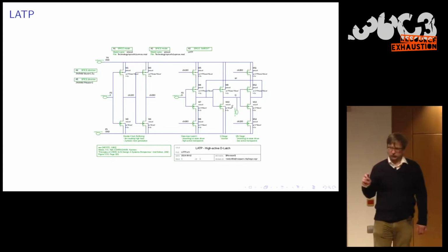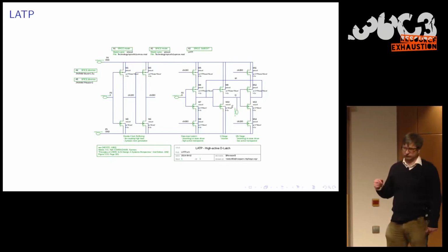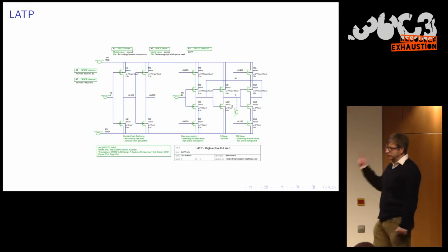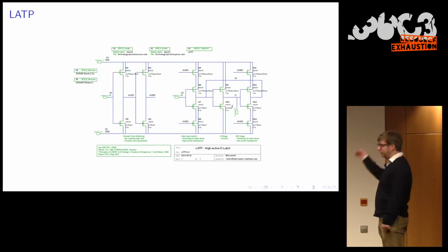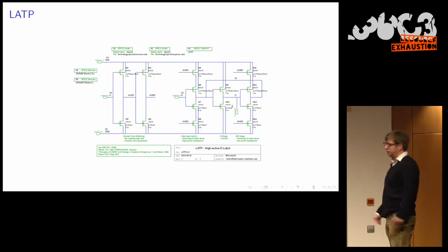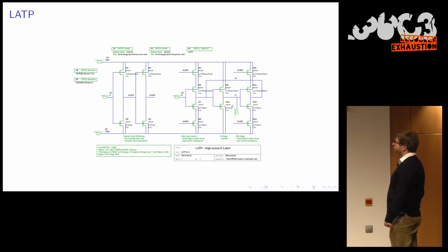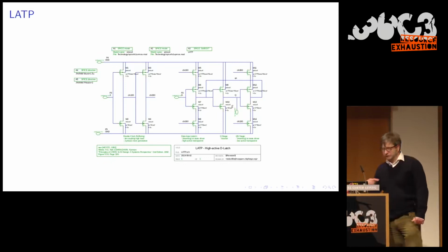These are memory cells driven by the clock, taktzustandsgesteuert in German, and in America it's just called latch. If we look at a high level, this thing is transparent, and at a low input level, it saves the value.